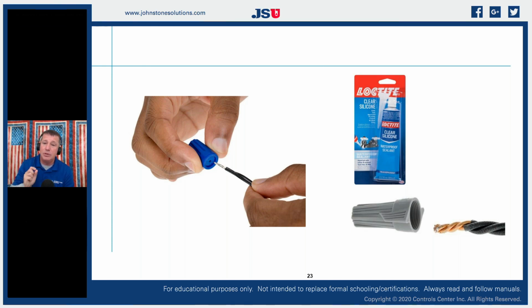We need to keep oxygen and moisture away from our copper. So what we need to do is make sure we have some clear silicone or dielectric grease. Clear silicone works great. That's all we're going to be using in most of those underground wire nuts, a good 100% silicone. So after you've twisted your wire nut together, have a tube of silicone or a caulk gun of silicone. Most of the time we already have silicone on our vans anyhow. And we need to fill that wire nut full, so that we can remove any potential oxygen or moisture from entering and creating oxidation and corrosion on that copper surface.